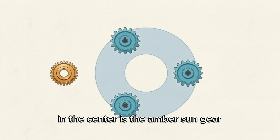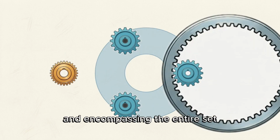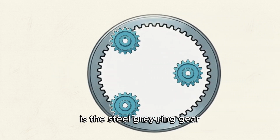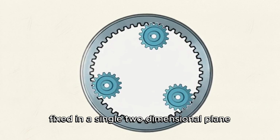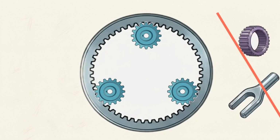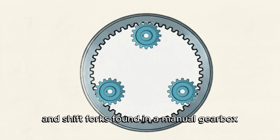A planetary gear set consists of 3 components. In the center is the amber sun gear. Orbiting it are the cyan planet gears and their carrier, and encompassing the entire set is the steel gray ring gear. These gears remain constantly meshed, fixed in a single 2-dimensional plane. This removes the need for the sliding collars and shift forks found in a manual gearbox.